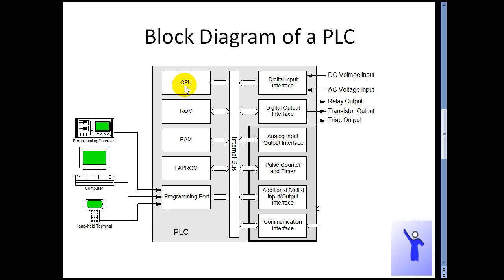the output accordingly. This is the read-only memory which teaches the CPU, which probably knows just a few machine code, how to run user programs and how to interact with various other devices. This program on the ROM converts this CPU to a PLC, and the code on this ROM will probably be written by the manufacturer of the PLC.